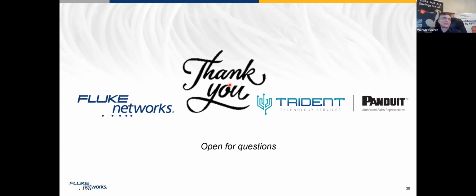We don't have time, but we also, of course, do fiber testing. Fiber is also used in industrial environments for several reasons: less electromagnetic interference influence, longer cable, more data, higher bandwidth, etc. But the other side is that it's more sensitive to dirt, especially in more dirty industrial environments. So again, you need to test. There is nothing very specific to test that differs from an enterprise environment: loss, length testing, OTDR testing to see if there is an issue and where the issue is. Is it the connector? Is it the splicing?